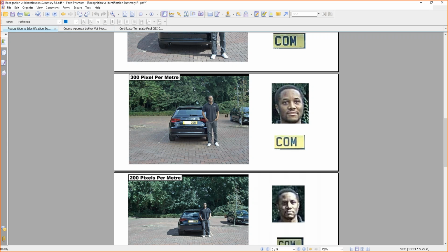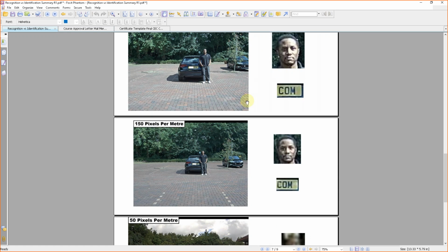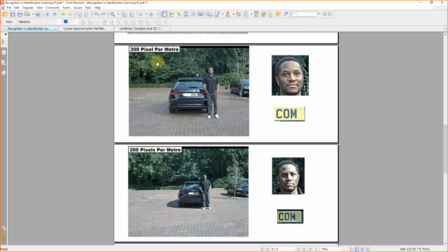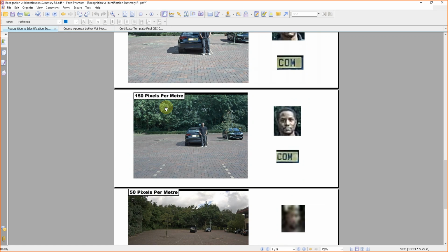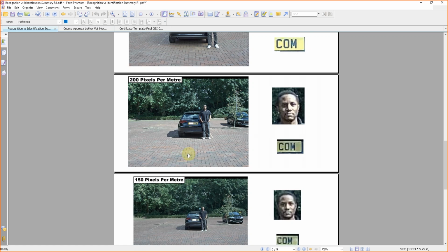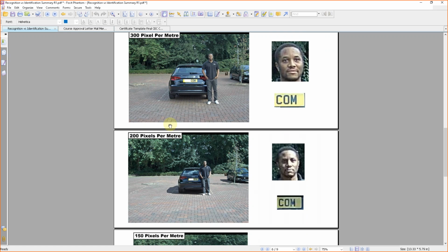If you do that, you will end up needing 10 to 20 cameras to cover the entire parking lot, because your expectation is 300 pixels per meter. You cannot say I need identification in my entire project. So you have to have a good balance: where you need detection, which areas use identification, and where recognition is needed should be clear. Very simple thumb rule.